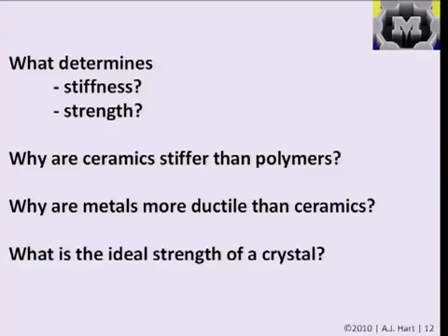Polymers are typically long chain molecules, like carbon fibers, for example, or something like Kevlar, or the fiber in a synthetic piece of clothing, which is made by making a polymer solution and spinning it out like you might extrude spaghetti, but at very high speed, and then treating it so you align those polymer chains with the axis of loading. The type of those bonds, basically what atoms you have connected to one another, and the characteristics of that bond are going to determine the stiffness of the material, and the organization of the chains, and the gaps between them, the sort of defects, can relate primarily to the strength of the material. Everything is coupled, but that's a basic picture that we'll start to build upon.